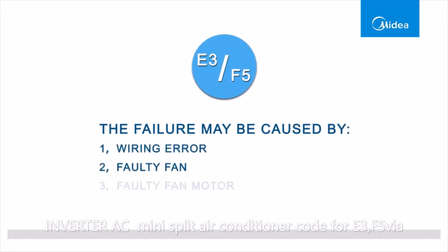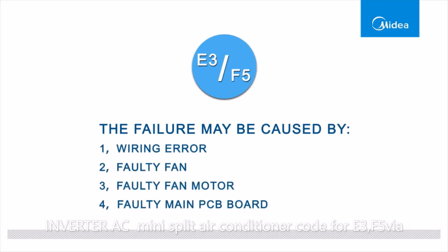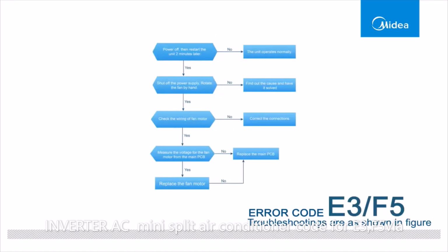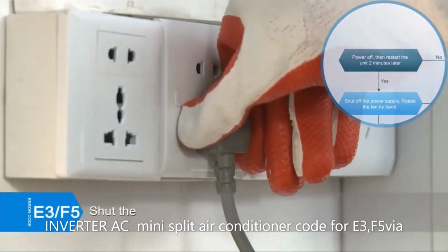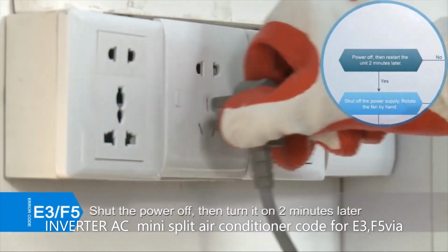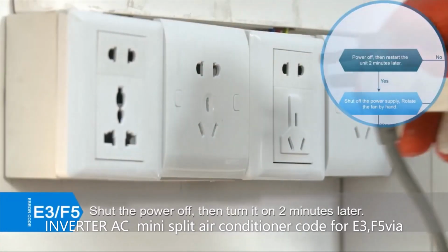The failure may be caused by 1. Wiring error, 2. Faulty fan, 3. Faulty fan motor, 4. Faulty MAIN PCB board. Shut the power off, then turn it on 2 minutes later.